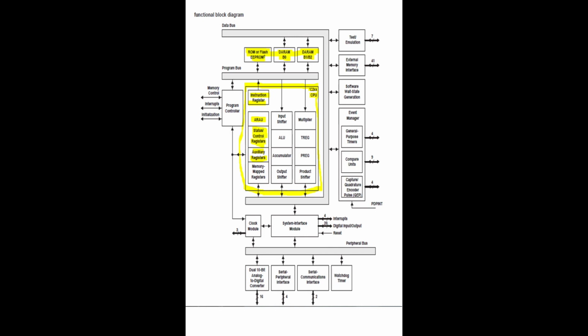So this can be used for indirect addressing. It is a register. We know that in indirect addressing, the address is not given directly. The address will be in a register. First you go to the register and get the data, that means get the address. In that address some content will be there. This is indirect addressing. Similarly here, for indirect addressing, AR0 to AR7 will be used, auxiliary register 0 to auxiliary register 7. If you want to access, you can use 000 in a bit in a control register.